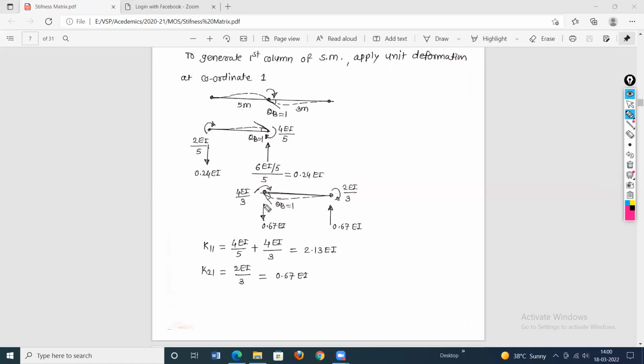Then in a similar way, the moments at the ends and the resistive couple magnitude are determined in the second part. Now the second part is deformed in a downward direction as shown here. So this deformed shape is shown here. What is the slope here? Theta B. Now we have applied the moment at B point in a clockwise direction. How much moment is required to apply? It will be equal to 4EI by L. Now the length of this span is equal to 3.